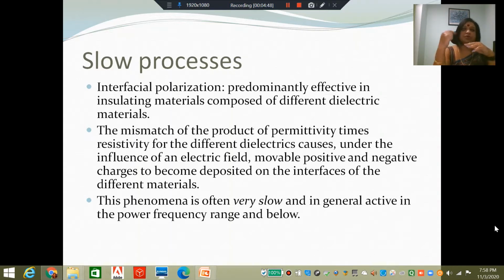and therefore that may have a higher voltage fall across the material, even if these materials are of the same thickness. The lower permittivity material will see high stresses, the higher permittivity material will see lower stresses, and accordingly there will be the voltage division. On top of that, you see E, and then the current that flows through the material depends upon the conductivity as well as the electric field.